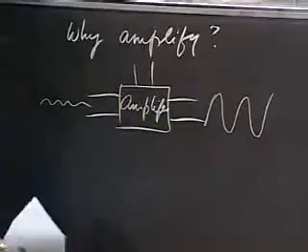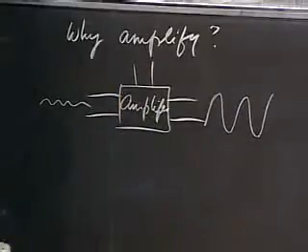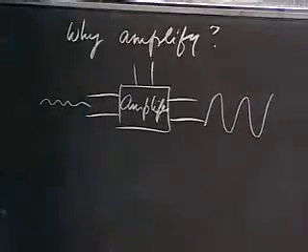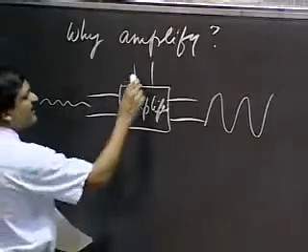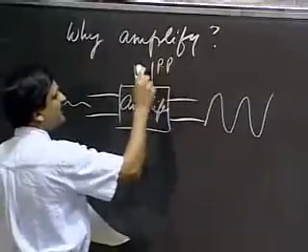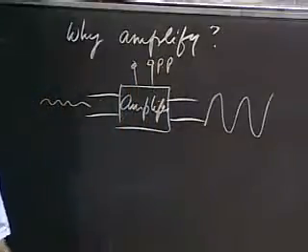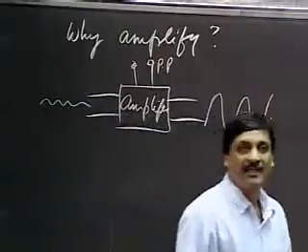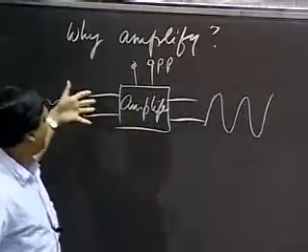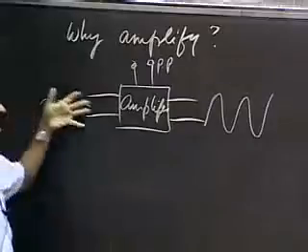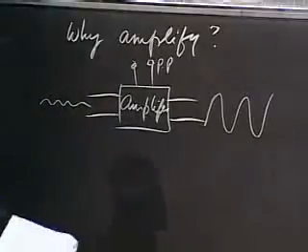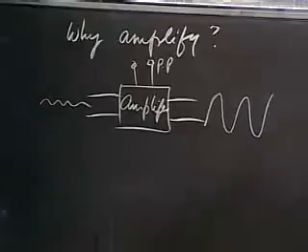And commonly, the amplifier, in addition to an input and an output, input port and output port, may also contain a power port, okay? So that I can apply a power supply to the amplifier because commonly, as I amplify a signal, I'm looking for a power gain as well, an increase in the power provided by the output.